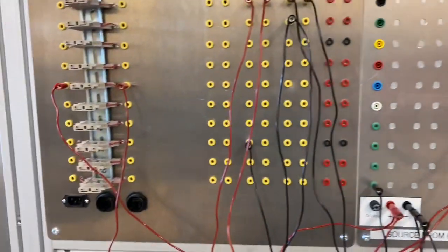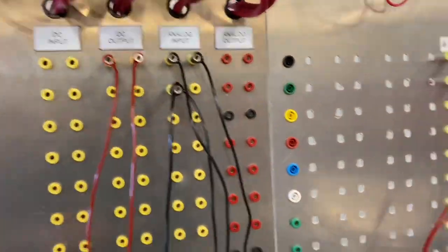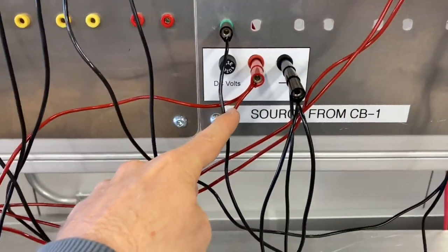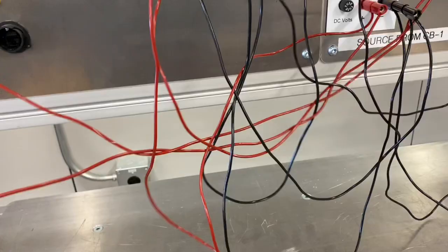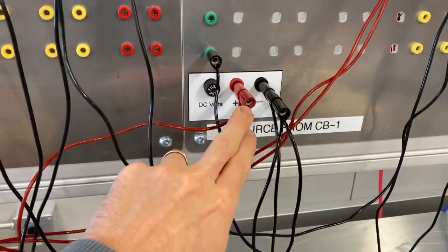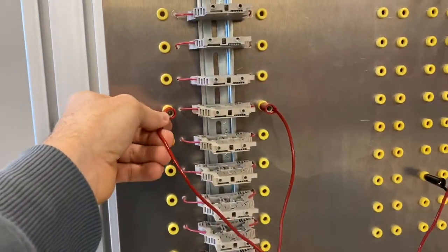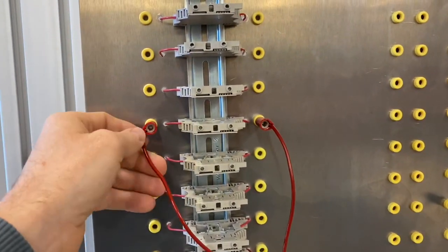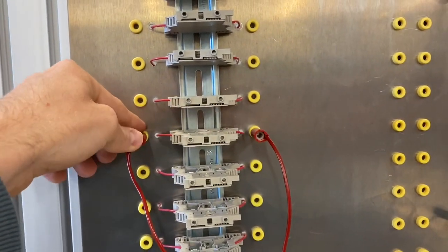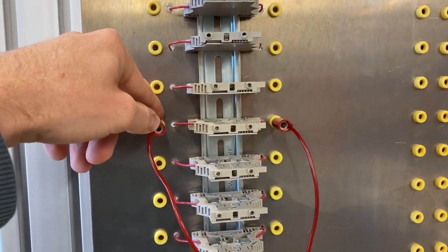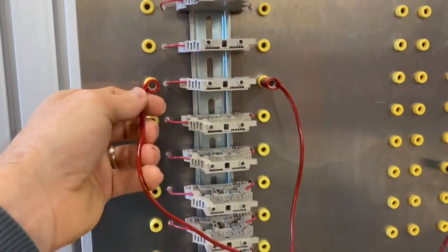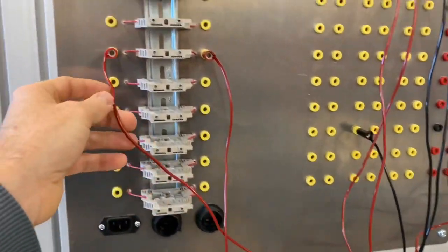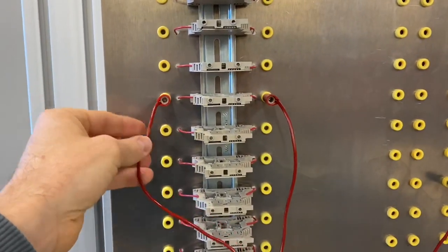Looking at the analog input now, you can see we start over here. Power runs over to our fuse. I've got this one fused. The reason I didn't fuse the output is because all these fuses are only rated for about 100 milliamps, and the solenoid needs 500, so we'd blow the fuse. I didn't have a big enough fuse, so for now I left it unfused for this demonstration.